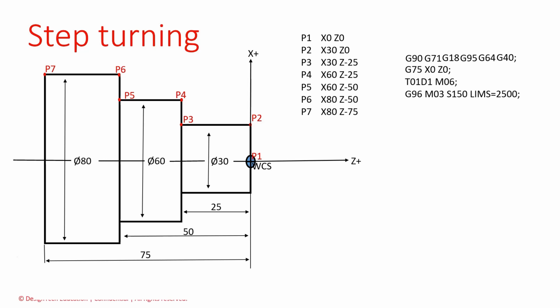That safety point we mentioned is based on the workpiece. Our workpiece major diameter is 80 millimeters. Above the 80 millimeters we have a safe point, for example 82. The Z-axis also maintains a safety point. The safety point value is G00 X82 Z2.